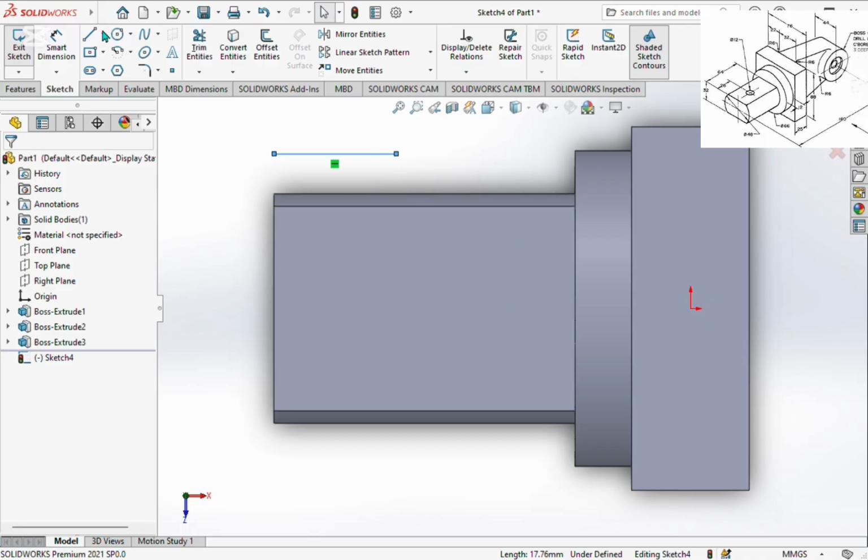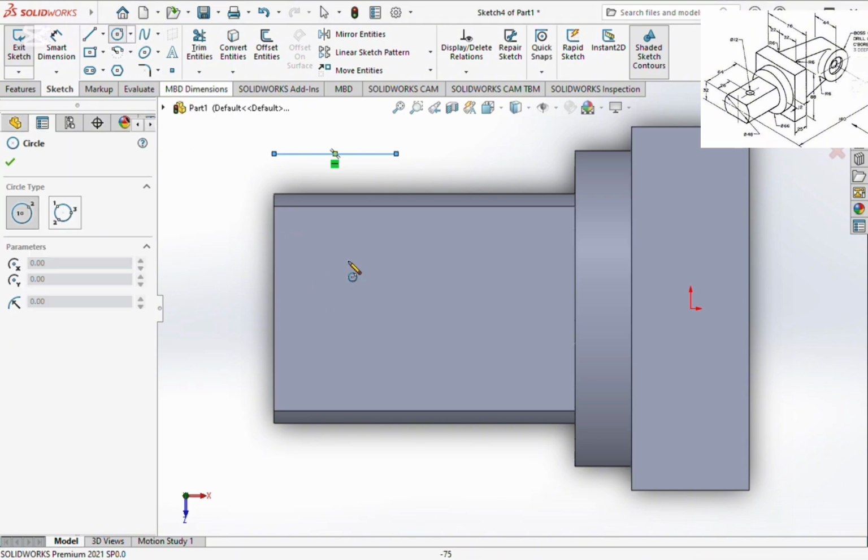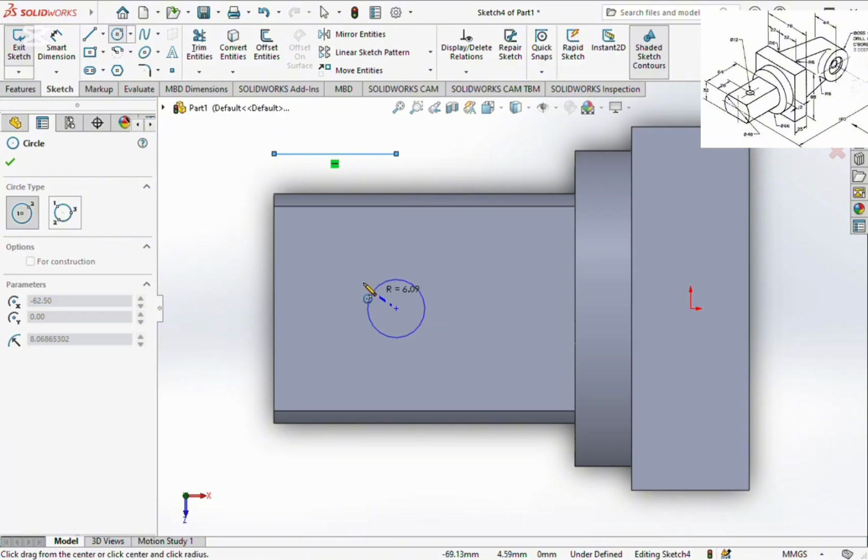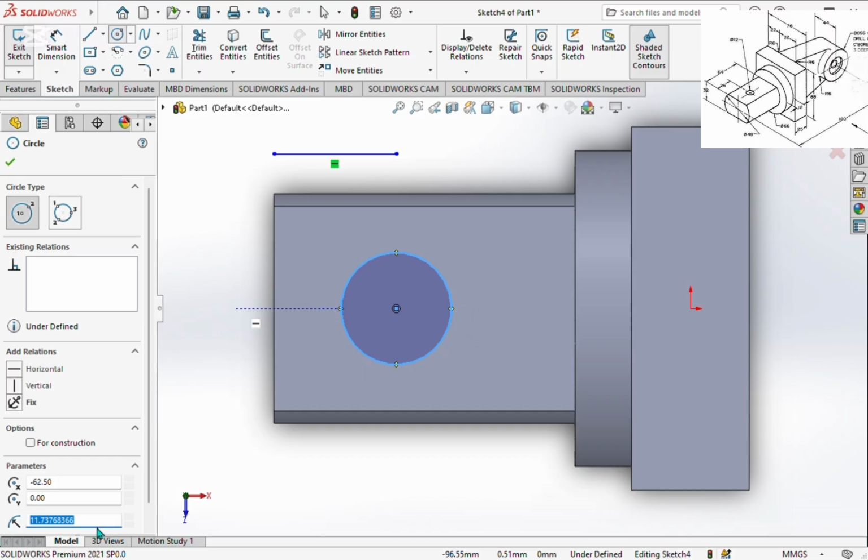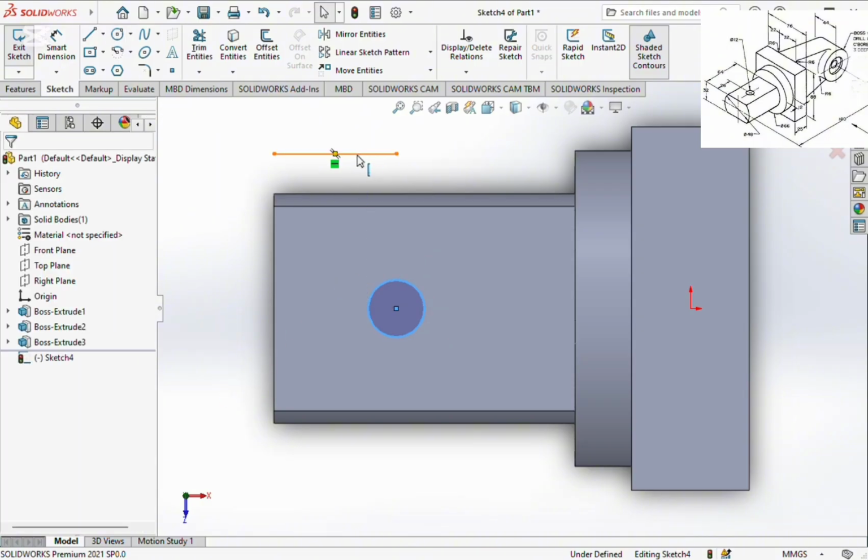The line increased forward. Now, what I need now, I will just take my circle command, because I already know the circle will be centralized and at that 26. So I take my circle command, my center circle, or normal circle command. Now I highlight from this point of the line to the center of the figure as I have it there. As you can see, when I do that, I'll just draw a circle. You can see it intersect up and down. So just draw a circle, then edit the radius. So the radius is 6 because the diameter is 12. So that's what I have there.